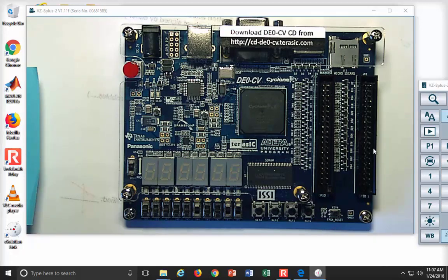Notice that when we use ModelSim, we are only simulating. When you use this, you are synthesizing. Now, the labs in general, going up until about the computer lab, you don't necessarily need to simulate them, so you can spend your time just synthesizing, even though in the real world you would usually simulate it and get it working, then you would synthesize it. But these are simple enough that you can skip the simulation step.